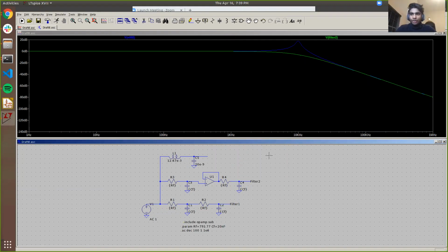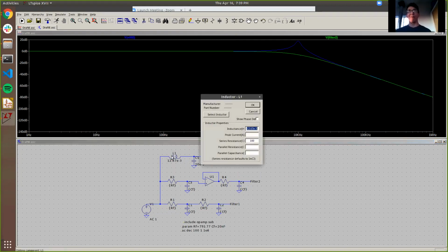Why was 500 milliohms an absurd equivalent series resistance value for your inductor? That's a great question. If you're using an inductor to filter a powered signal, then having 100 ohms as your ESR for your inductor is the same thing as having a resistance in series with the inductor of 100 ohms.